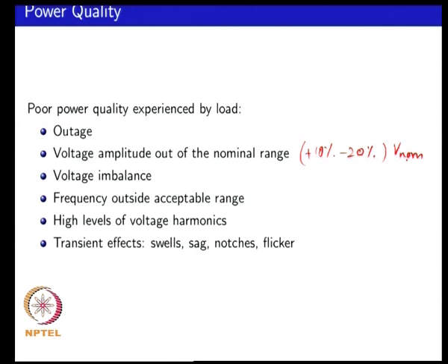You might have, say, voltage imbalance. Your voltages might be close to nominal, but your phases may not have equal amplitude voltage, or there may be some phase shifts. It depends on the type of load. For example, if you are feeding single phase loads, then the imbalance may not be a major thing, but if you are feeding, say, an induction machine load, then even an imbalance of 3% would be considered unacceptable.